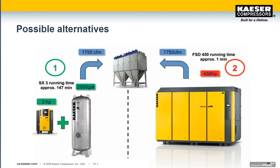This type of operation is going to lead to service-related issues on that big 450 horsepower compressor and likely premature failure of major components. Not to mention the capital cost to purchase a 3 horsepower compressor and a 2,500 gallon receiver is going to be only 20% of the cost of a 450 horsepower compressor. So the whole point here is evaluate your point of use demands before purchasing large equipment.